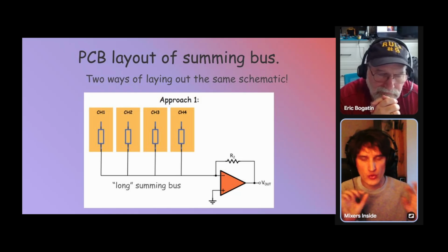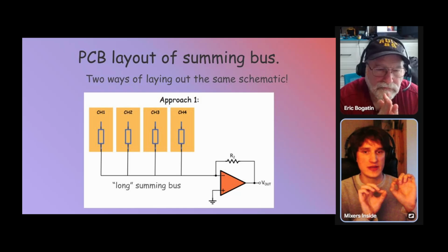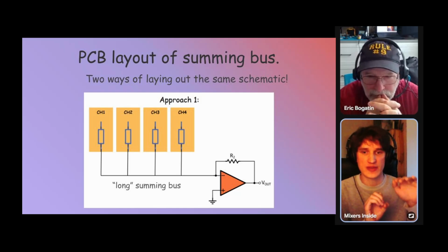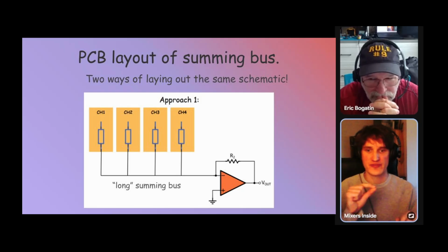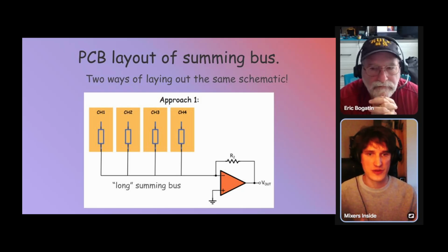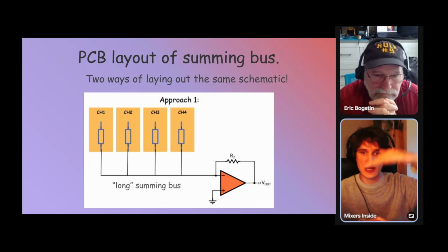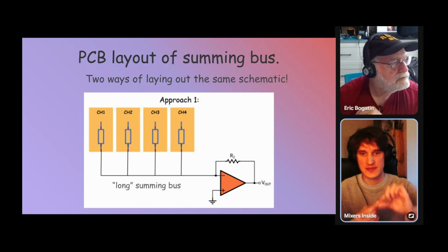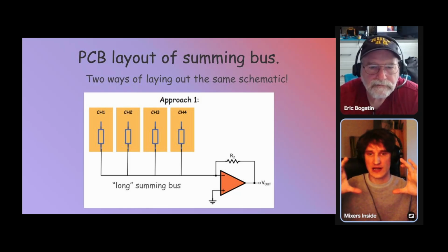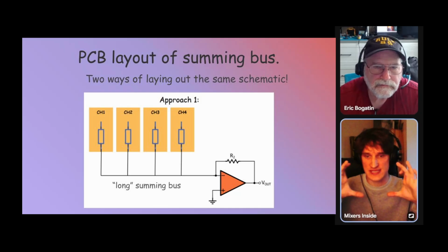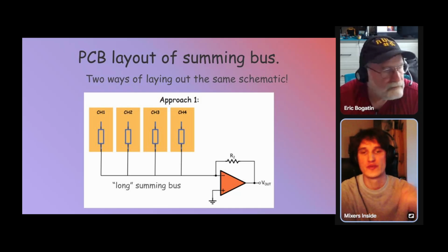And we all agree that running signals through this kind of connector with one ground pin is very bad due to crosstalk, because the signals are referenced to the same thing, and the loop area becomes significant, and the signals interfere with each other.